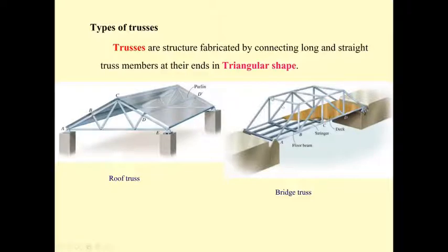Also, on the top of the truss, they use these beams to connect the trusses to each other. After that, they lay the stringers along the length of the truss, and finally, they construct the floor over the whole area of the stringers.